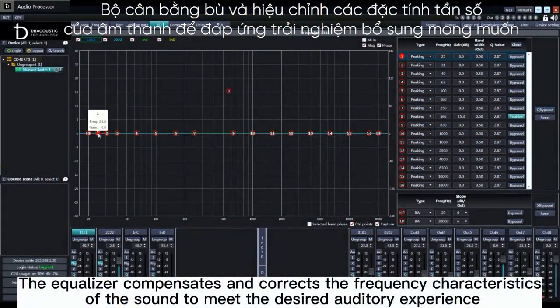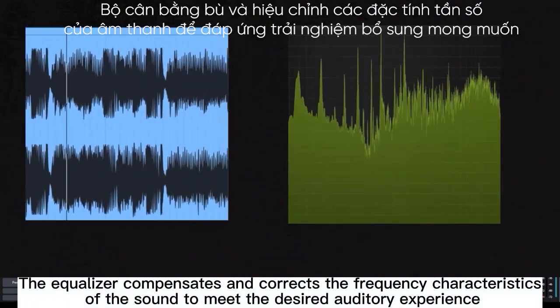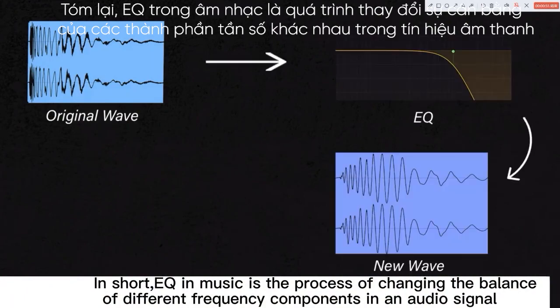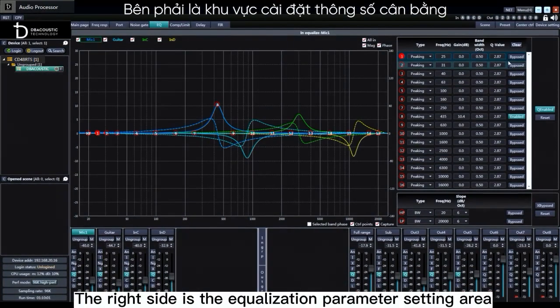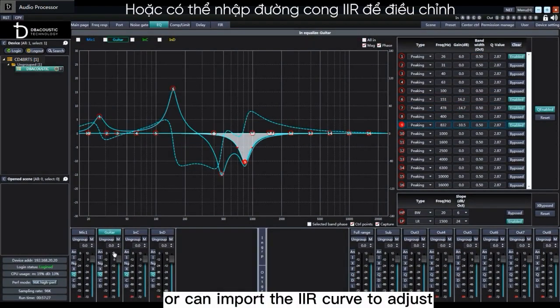EQ setting. The equalizer compensates and corrects the frequency characteristics of the sound to meet the desired auditory experience. In short, EQ in music is the process of changing the balance of different frequency components in an audio signal. The left is the curve for input and output channel. Show magnitude curve and phase curve for each channel. The right side is the equalization parameter setting area. Can be adjusted on the curve directly, or can import the FIR curve to adjust.